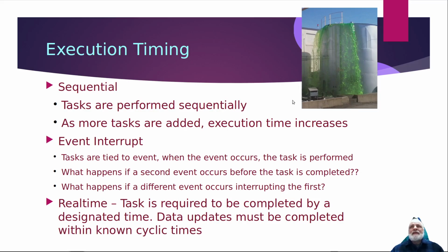So when you run down through the program, it checks the sensor and says, okay, the tank is full, shut off the pump, right? The message that the tank is full comes into your controller, and then your controller says, oh, well, let's shut off the pump. But a minute before, the tank wasn't full, so it did not shut it off. Then it comes back up, loops around, and checks again.